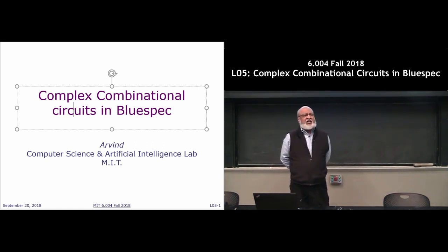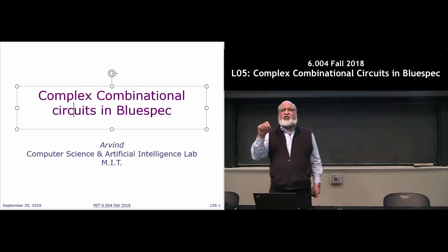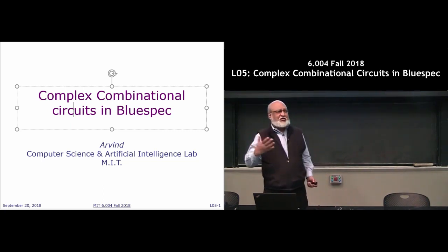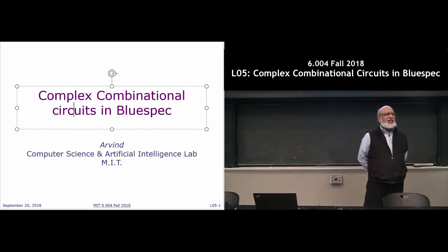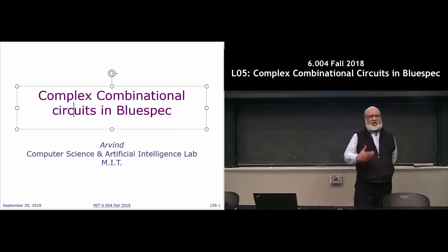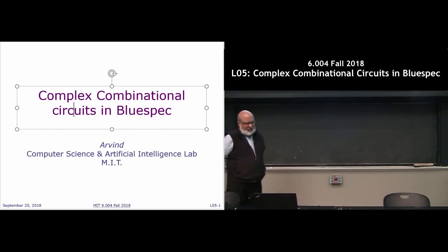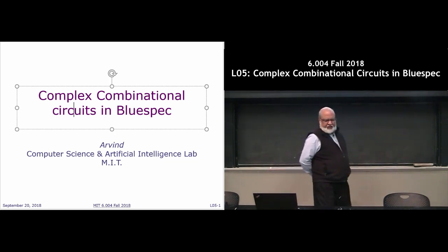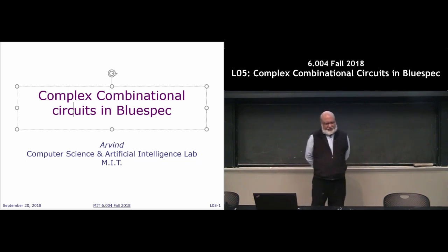The question comes up, if I want to write a W-wide adder, which adds W bits, then what do I do, right? So in my code, I can't write dot, dot, dot. I mean, that's not going to do, right? So we have to find some other way of doing it. So today's lecture is somewhat about how to generalize this to write a W-bit adder, which means parametrized circuits, where you are parametrizing it first and foremost by the bit width, but there will be many other parameters in these circuits. Okay, so a W-bit ripple carry adder, we cannot write straight line code.